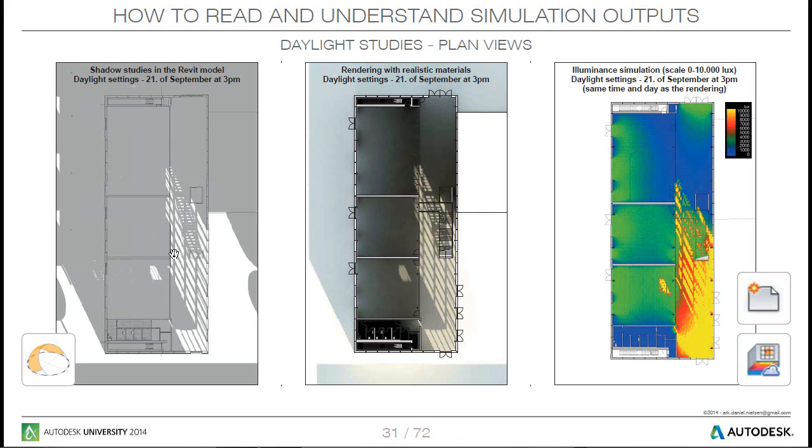In the same way, if you didn't know, we actually can make shadow studies as a section without, so to say, losing the geometry above. So this is actually the shade pattern inside the building. So it's similar to the perspective view, and it's interesting to look at both, so to say. And of course, when you are looking at design concepts or different options, then you should compare them in a similar way as I showed earlier on with a different proposal, but I have not in this one.